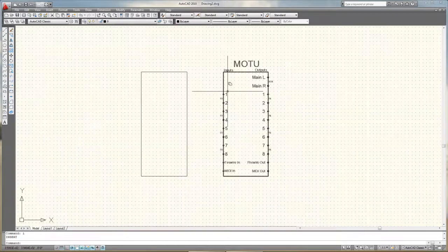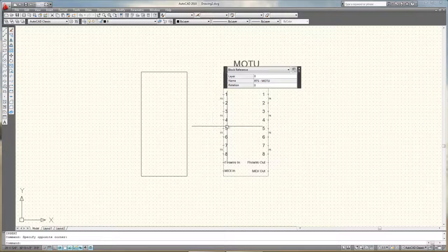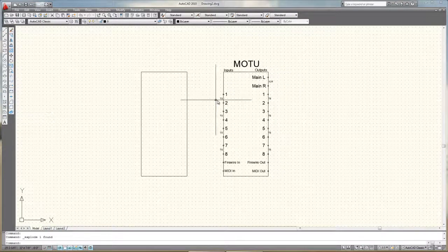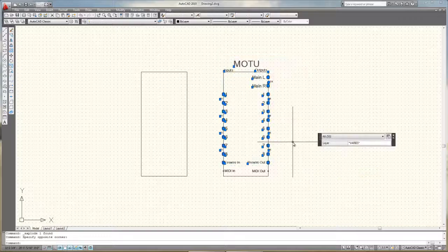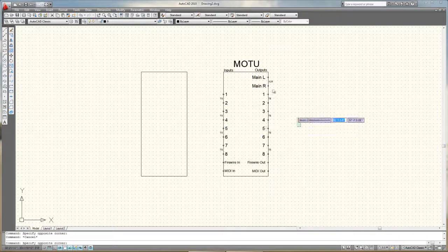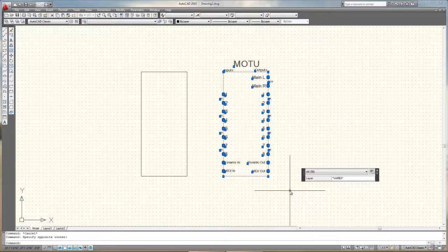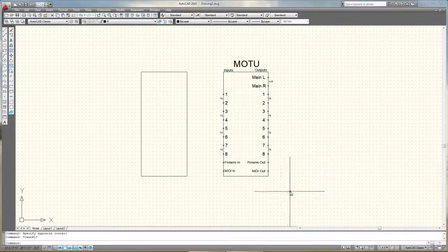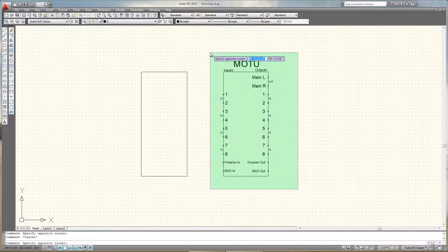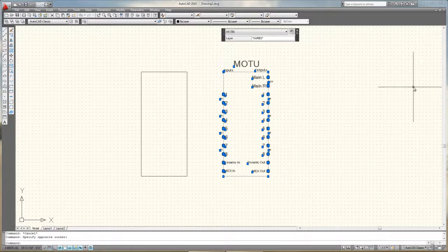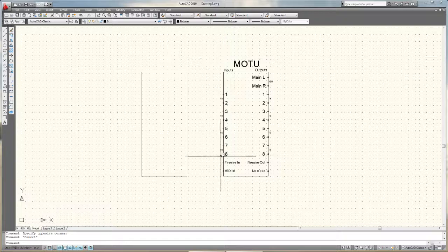But what we're going to do here is recreate this. So the very first step is to explode this, and that's right here. Now everything, and I've just tapped that, you can see there's no longer one pick point. Everything is its own icon: there's text, there's a square here, there's little circles, there's smaller text, everything's a big mess. It's less convenient because if you have a cluttered drawing, in the sense that everything's clumped together to get it on a page, it's really annoying to have to move it around with all this text separate. That's why blocks are really helpful. Plus, obviously, blocks can be created into a database and then imported into any new drawing, as you've seen me do with this originally.